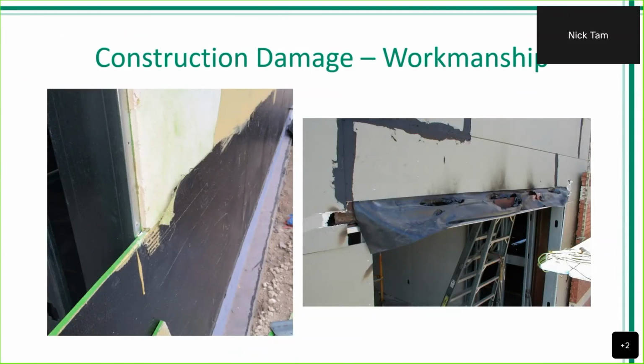And on the right, this is a really good example because in some situations, we may have a perfect installation of our flashings, our transition membranes, and we're good to go. But then somebody above is deciding to weld, well, you get enough sparks flying down at those membranes, they will damage them. And you have to think about safety at that point too, because a lot of these peel and stick membranes that are going to be used for transition are going to use solvent-based primers. If a bucket of the solvent-based primer is opened up at the bottom and somebody's welding, be prepared because there could be some litigation should a fire hazard occur.